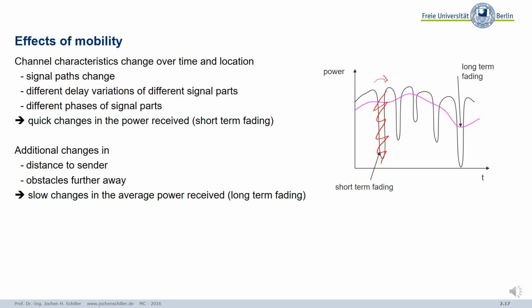So for example, the classical GSM system has a data rate over the air of, let's say, 22 kilobit per second. But what you can use is only roughly 10 kilobit per second. Why? You use a lot of forward error correction. So you insert a lot of redundant data. Because in case of this short-term fading, what can you do? You lose some bits.